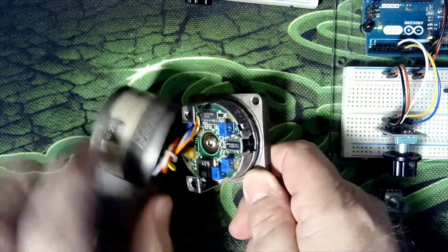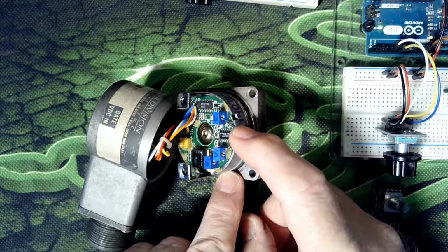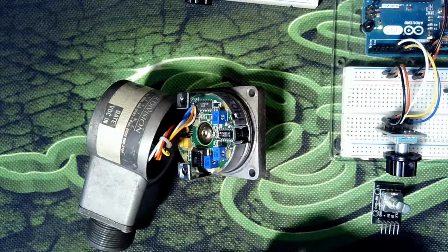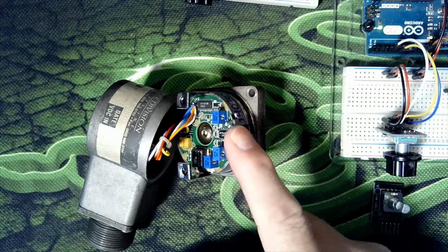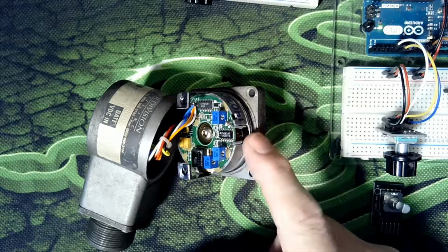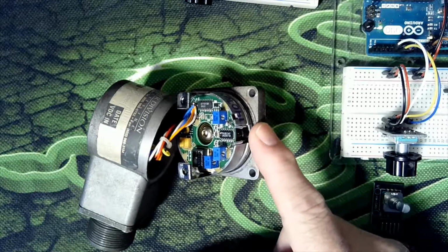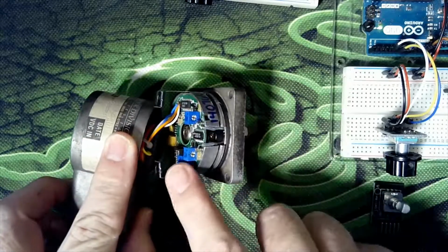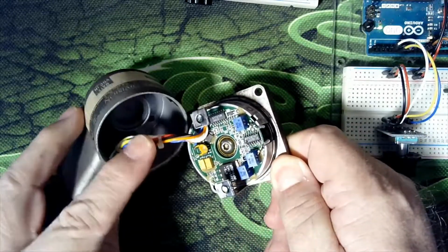Now, the detector is in this little chip here, this little long chip, and it has multiple sensors along it. So it's not just one, it actually has up to 6 on here, because there's 6 channels on this encoder. There's an A+, an A-, a B+, a B-, a Z+, and a Z-. And then there's a bunch of trim pots here to do some fine adjustments on the amplifier circuits, and a whole bunch of wires going out that we can tap into.